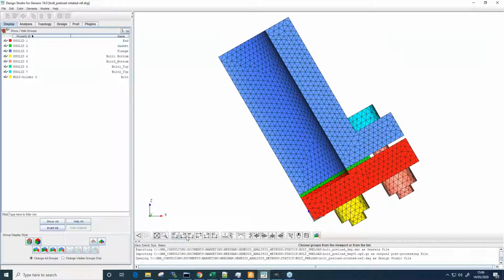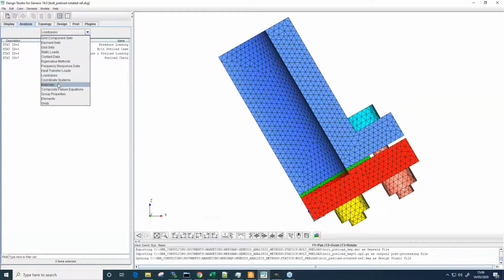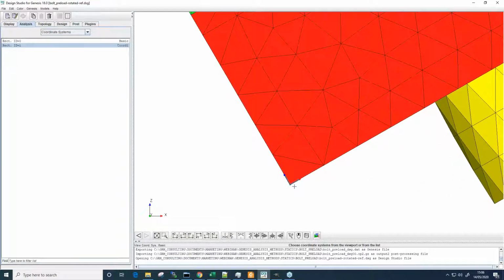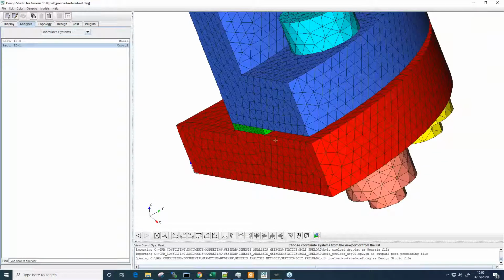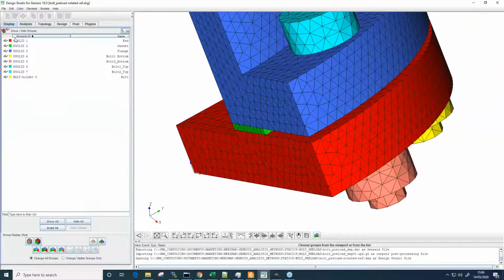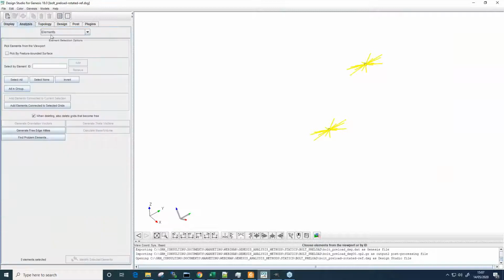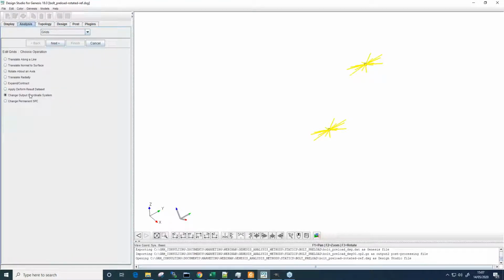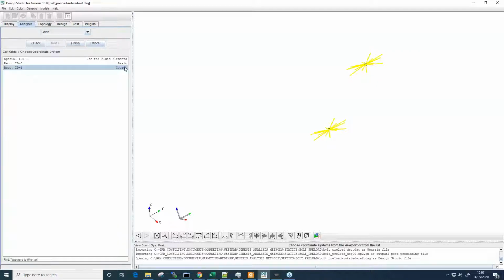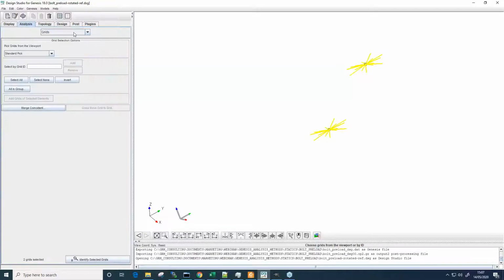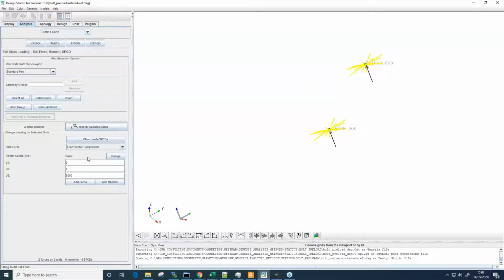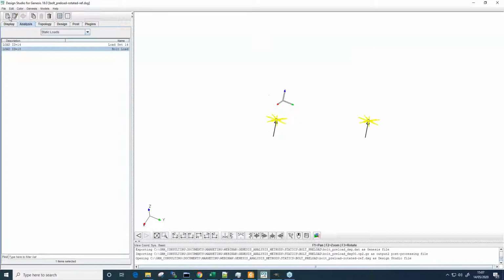So this model, if I do it in a standard view, you'll see it's all at a strange angle, and all we've done is created a coordinate system that we can see here is aligning along the axes in Z. And so we can do that very easily in the process. If I just look at my control grids here, in the grid selection, with them selected, I can just modify a grid and I can change its output coordinate system via the grids menu to my local one here. And that way it all works in that direction. And similarly, the static load that we have should be applied along the axes. And here again, you can do that by referencing the local coordinate system when you apply your force. And that's all done. Okay, that is bolt preloading done.